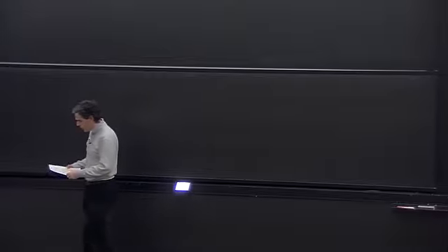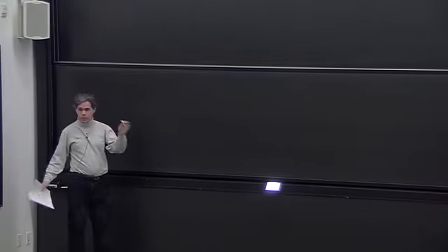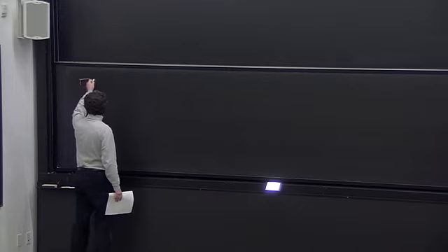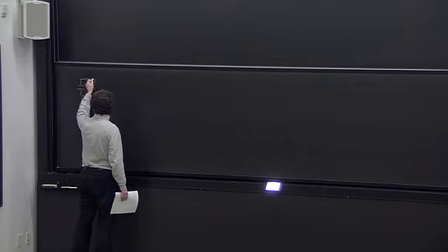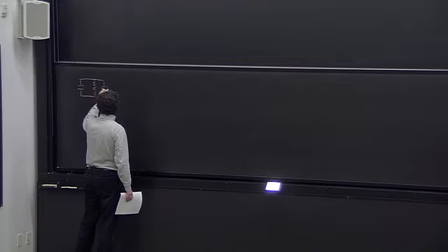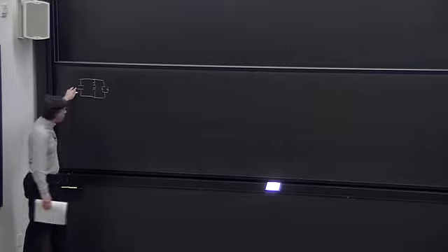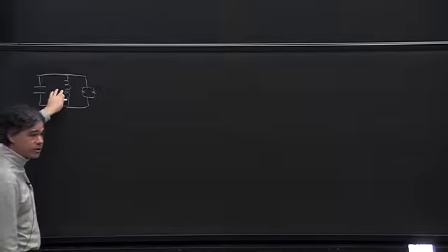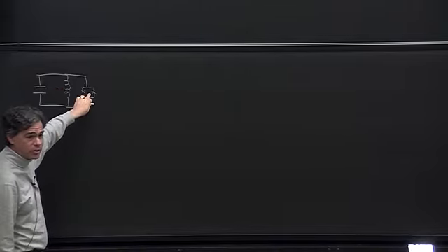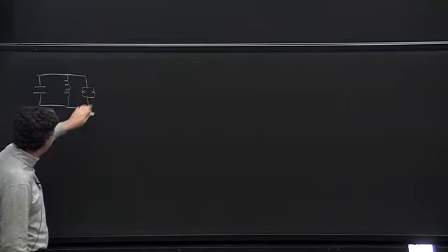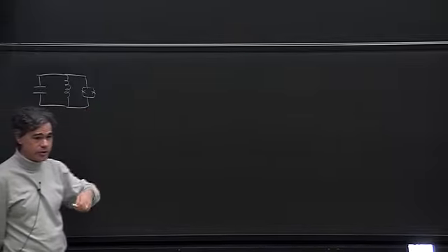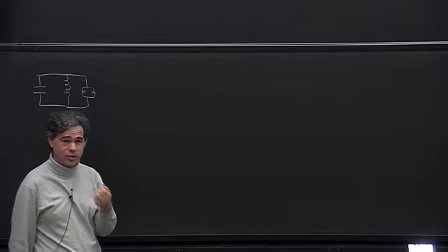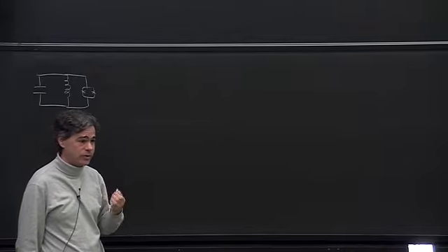OK, so like I said, all of these superconducting quantum computers work by using circuit elements. And so you can get some equivalent circuit to whatever they're doing that boils down to this, and then maybe something like this. This is a capacitor. Hopefully you remember that. This is an inductor. You might remember that as well. This one might not look so familiar. This particular thing is a Cooper pair box, and the X's are Josephson junctions. And the Josephson junction is kind of the key superconductor thing that lets you do interesting stuff.